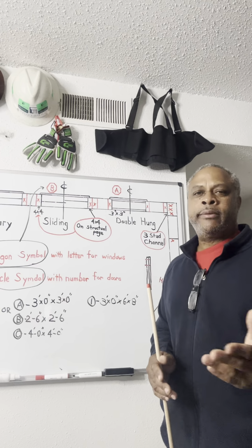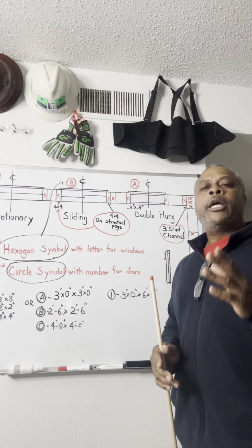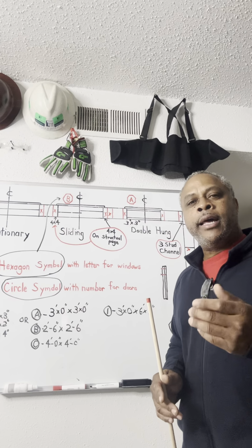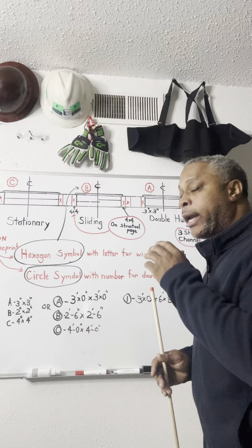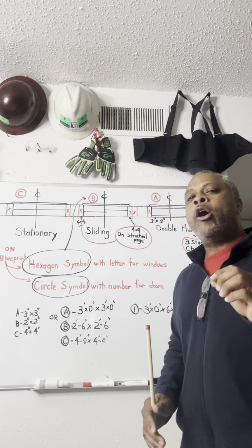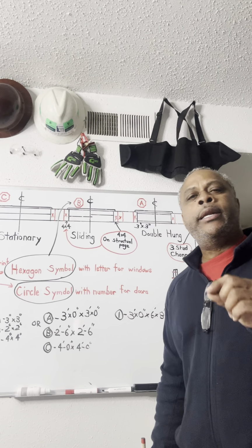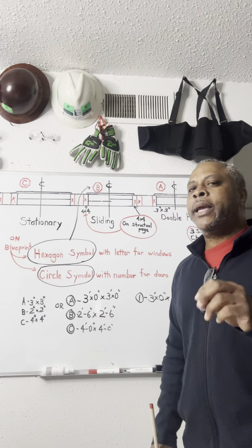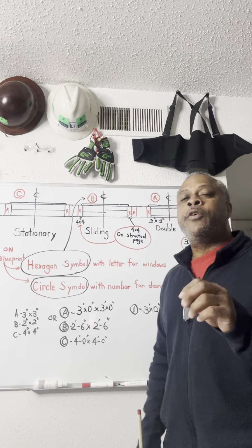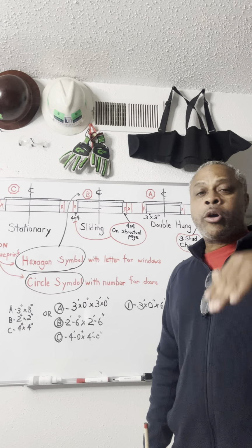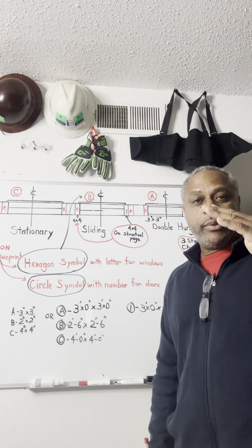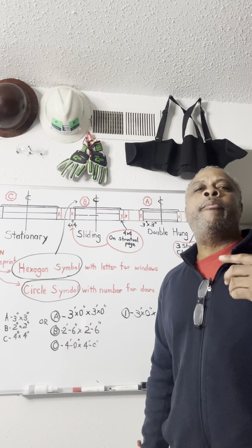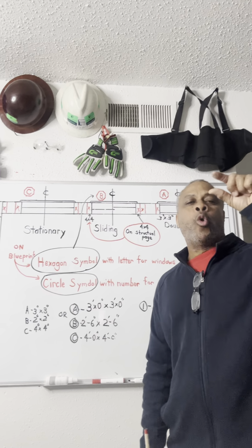You can float that. It can look cockeyed as long as your opening is square, level and plumb. Headers need to be plumb. But I also want you to put your header not at 80 inches for your door. Your header needs to be higher than 6'8", which is the call out size for the jamb. You need 6'10", at least a minimum of 1.5 to 2 inches of room.